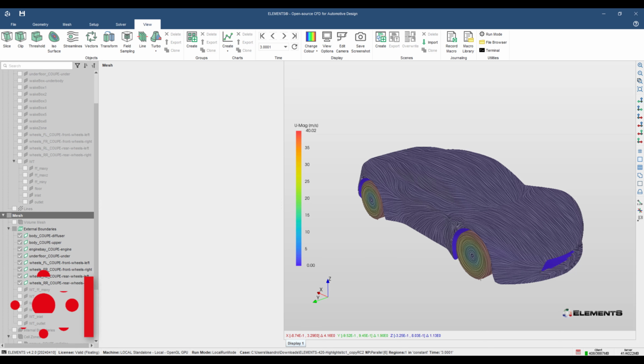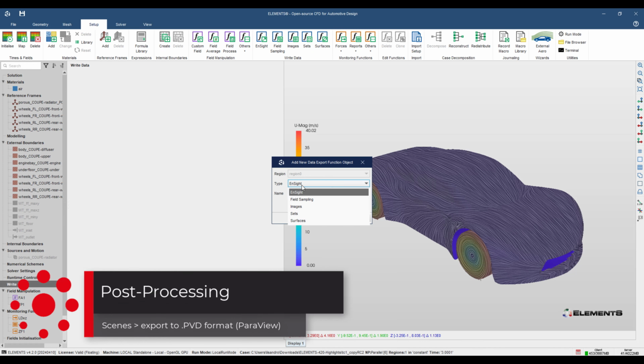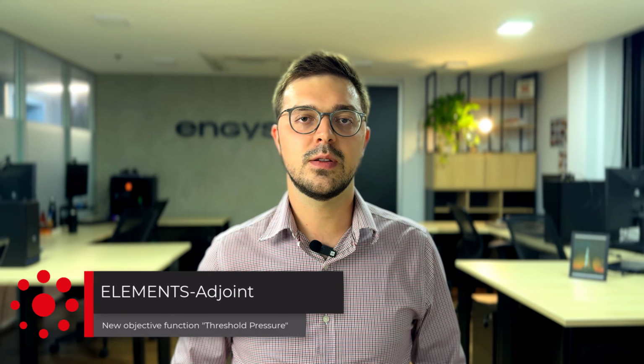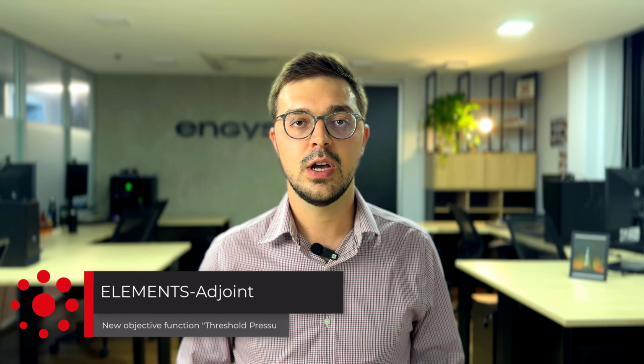To further support our users, we have ensured that scenes can now be exported in PVD format, allowing seamless visualization in the widely used open-source tool ParaView. With respect to Elements Adjoint, one of Elements' additional modules for topology and shape optimization, we introduced an objective function called threshold pressure, useful for cavitation risk analysis.